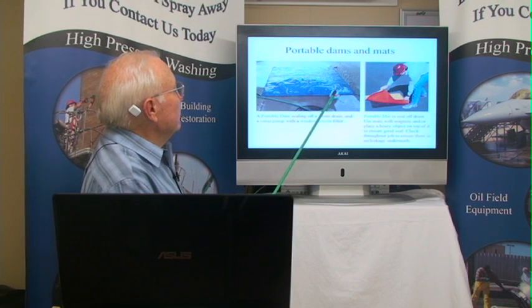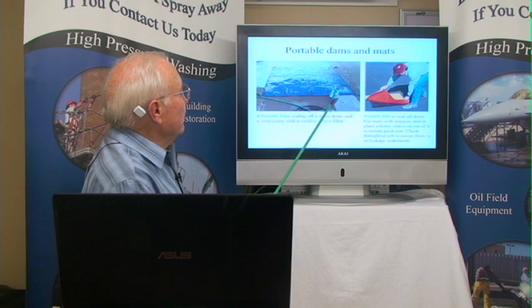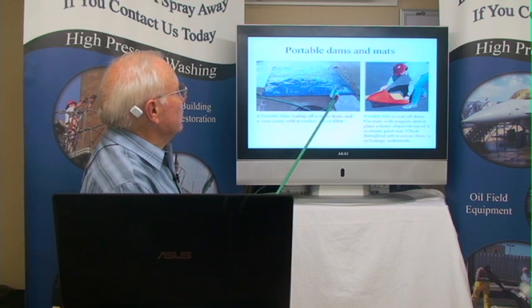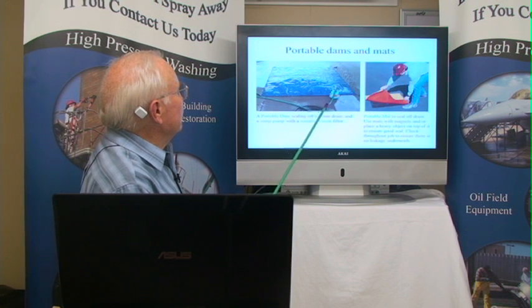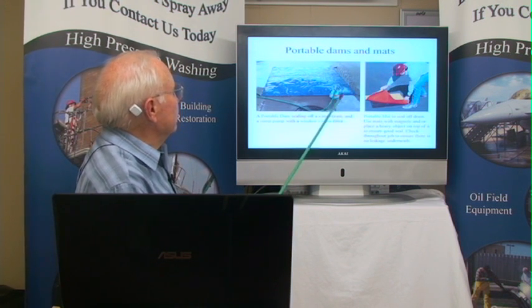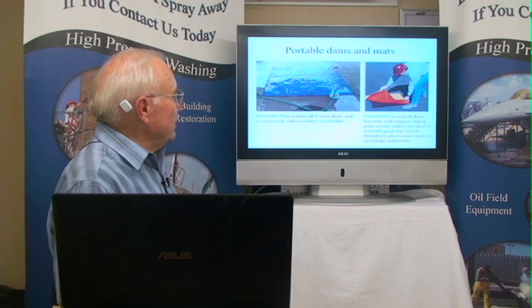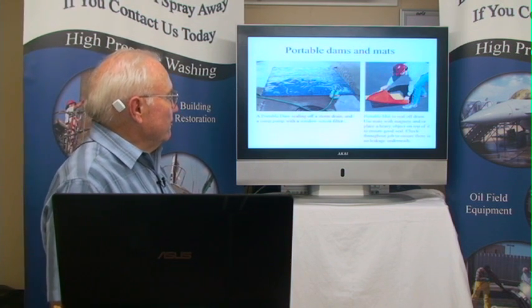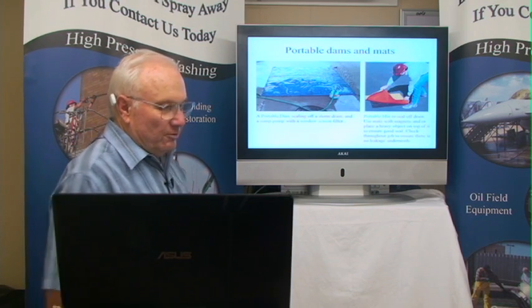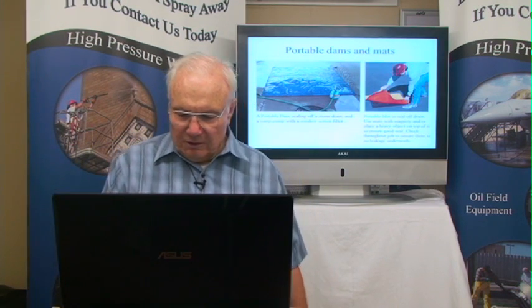This particular contractor has a sump pump, and around the bottom of the sump pump, he has a window screen. So now then he's filtering his wastewater, and I've seen a lot of times where they put a whole absorbent boom around here, and that way he can pick up that wastewater, and he's pre-cleaned and filtered his wastewater through a whole absorbent boom. I think we got a photo in a little bit that shows that.